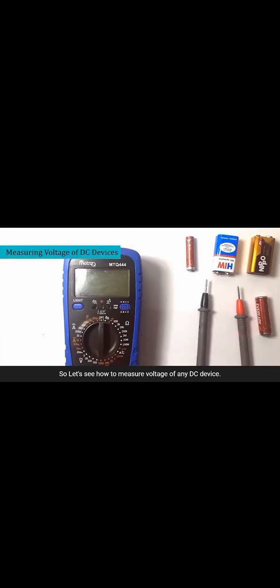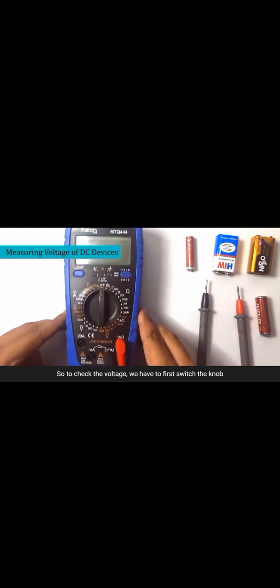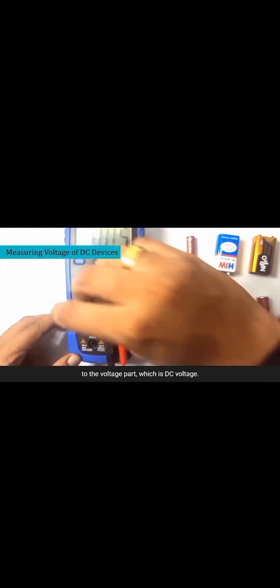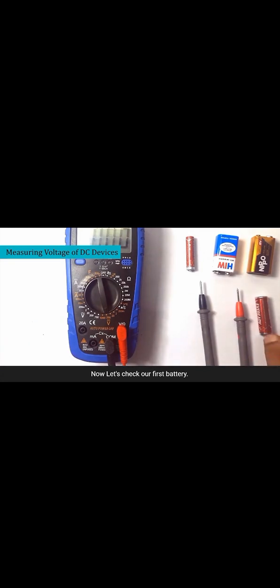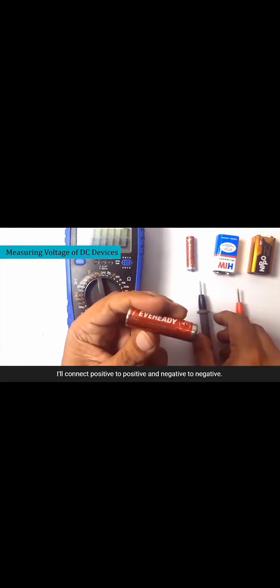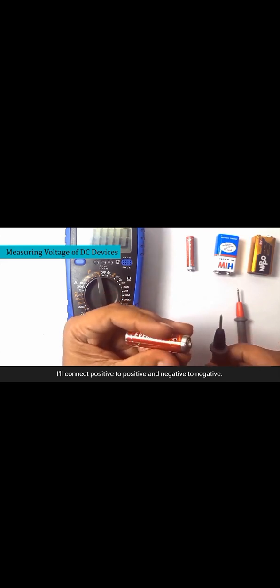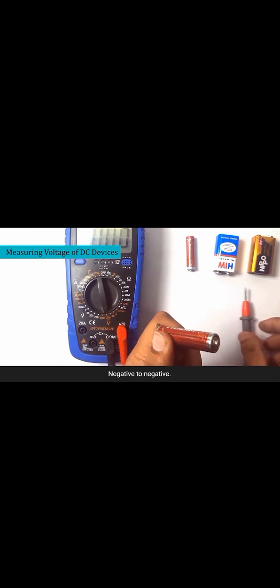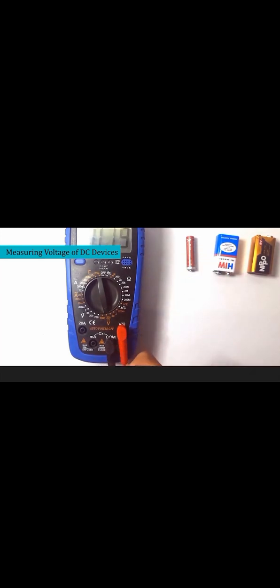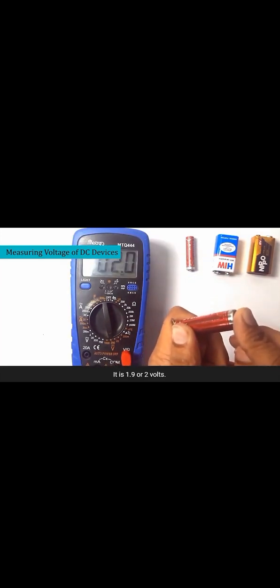So let's see how to measure voltage of any DC device. So here we have multiple number of batteries. To check the voltage, we have to first switch the knob to the voltage part, which is DC voltage. After switching this, we have to first check whether our terminals are properly connected. Now let's check our first battery. I'll connect positive to positive and negative to negative. It is 1.9 or 2 volts.